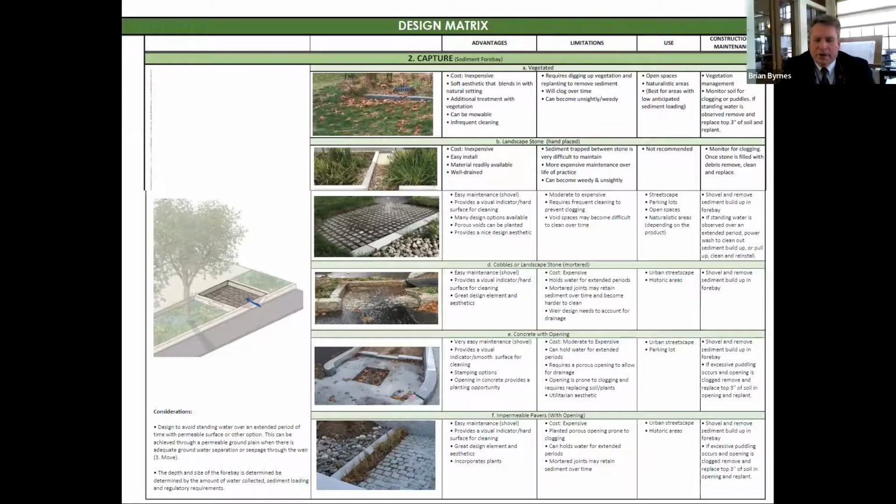Well, we're a historic park. I don't know, cobblestone seems like the most natural thing. We don't want anything that's going to look like it doesn't belong there. So I would say cobblestones, but I think this is where the sediment gets collected. And I've had problems in the past with my crews when it was a grassy area. They go to pull out the salt and sediment from the road, and they dig up the grass. So the grass never grows because they're just constantly digging it up because they don't know how far they're supposed to go. And they don't know where the sediment they're supposed to remove ends and the loamy base for the turf or whatever it is begins. So it's got to be something hard surface. I'm leaning towards cobblestones. That seems like the most natural thing to install there.